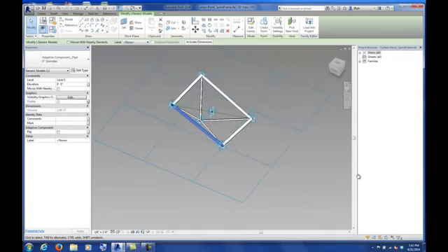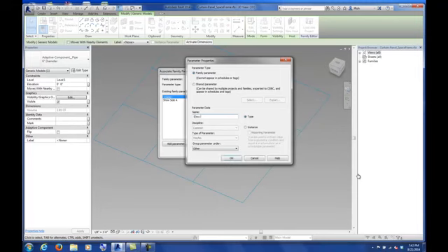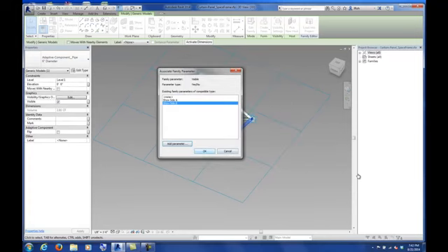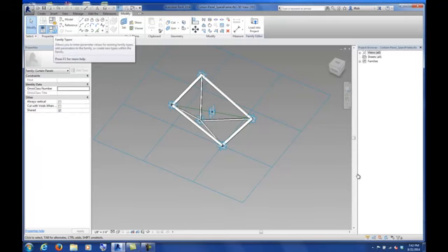I'm also going to go to a pipe that's 90 degrees, so I'll go to the one on the right here, and do the same thing. Visible, hit the button, choose show side B. Make that an instance, OK, and OK. Last step here, and then we're done with this component.